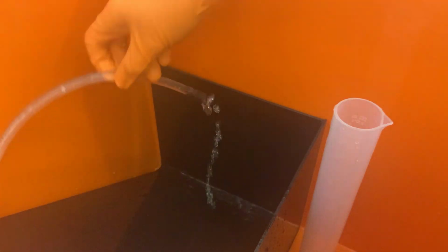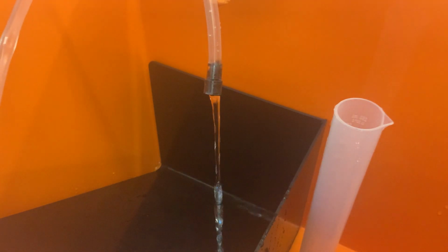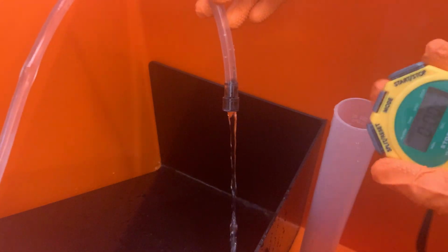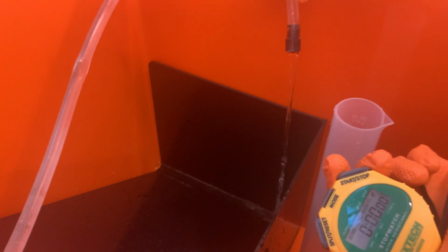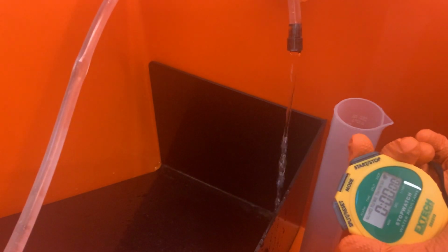Remember, we also have to collect the volume of water flow given a certain time so that we can measure the flow rate. So for that, you see this is the outlet coming through the pipe, right? And this is my stopwatch. I put it at 0. So I will just start both, collecting the water in this beaker here. So let's start.